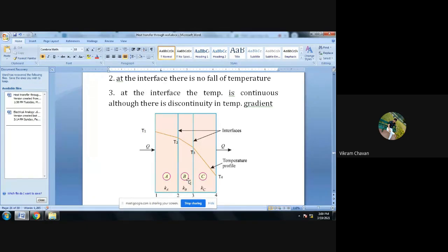What happens in general, we know that even a polished surface has some roughness. Roughness means there are some crests and troughs on that surface. These crests and troughs will form some voids when they physically contact another surface. Voids means small holes, and air will be trapped in those small holes. So we cannot say how much area is available for heat transfer at this interface point.